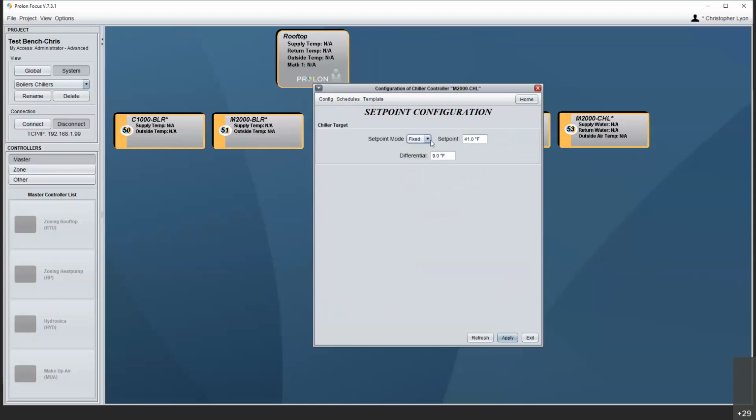Many times we see just fixed chiller set points. We don't do much for any kind of a reset, but you could apply a slight reset and gain a little bit of efficiency there. Big concern, especially when you get down south, is that we want that cold water for our dehumidification, even if we don't really need a whole lot of cooling capacity.